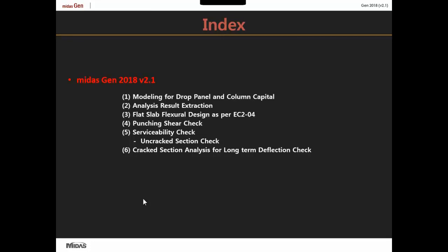Then flexural design of the flat slab as per EC2 will be performed. Then we shall see the two-way or punching shear check, and under slab serviceability check we will be performing cracked section analysis for long-term deflection check.